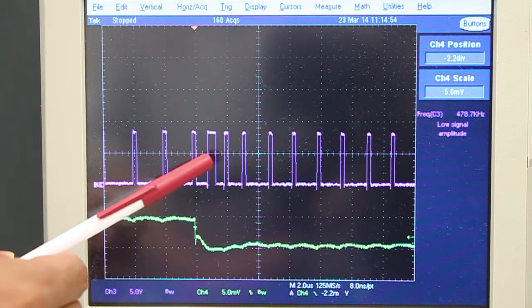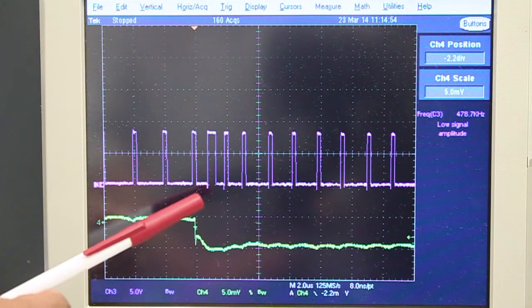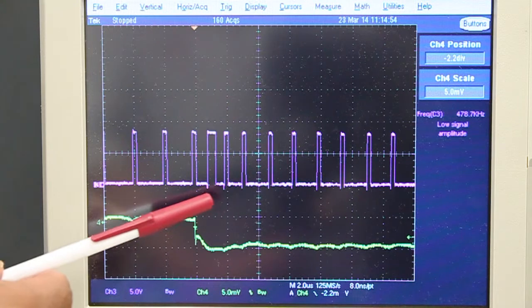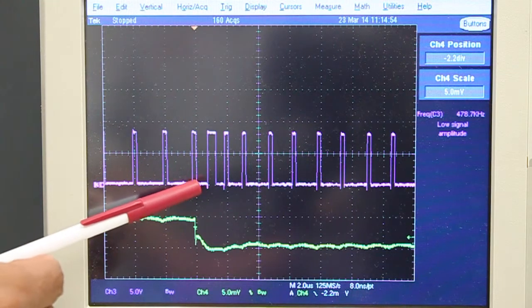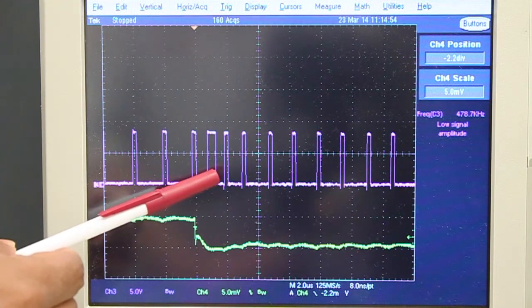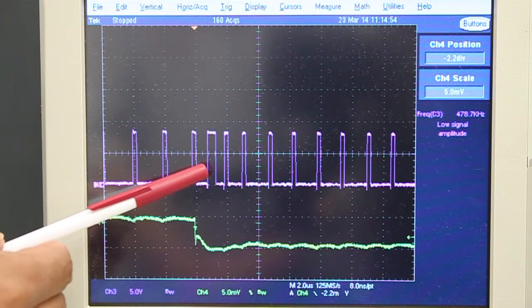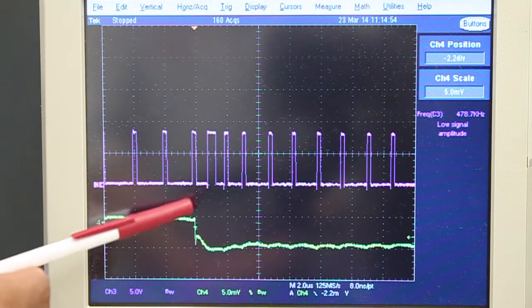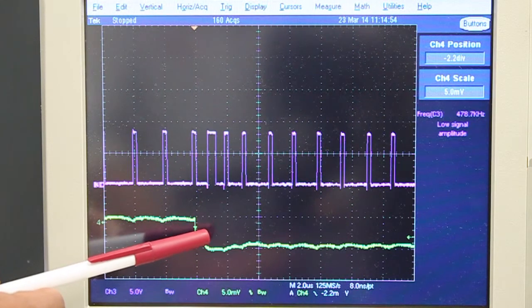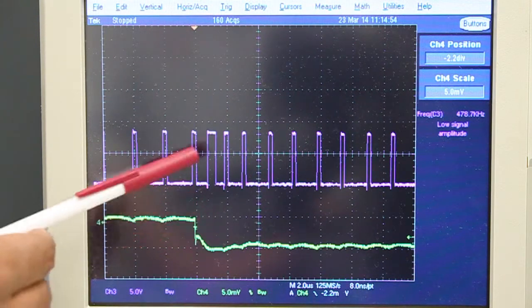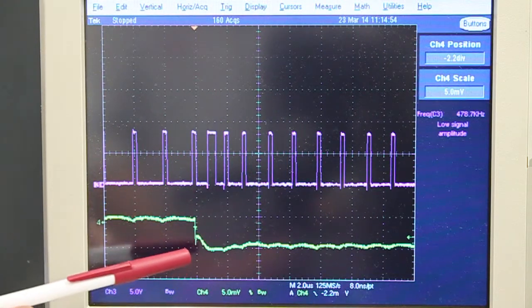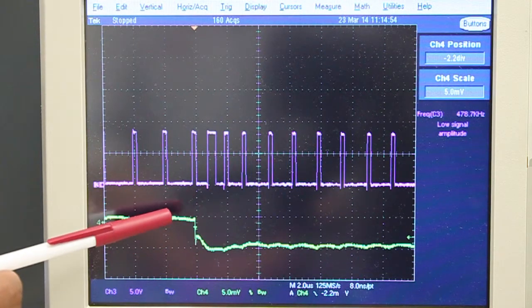Here now you can see the same setup and the same load transient response. The only difference is that we introduce our proposed control with the constant on-time control. And to show the load transient response, you can see that when the on time is extended using the proposed concept, the undershoot is much less than in the previous picture. So that's how we can increase the on time and improve the transient performance of the constant on-time control.